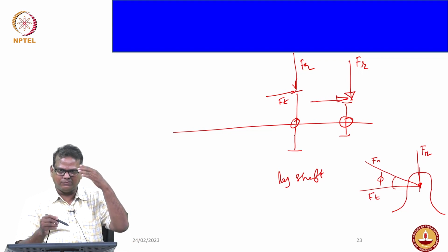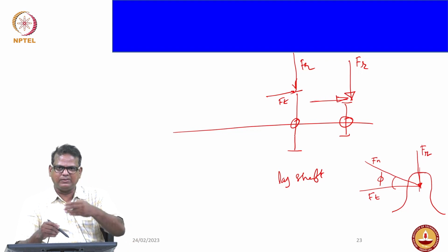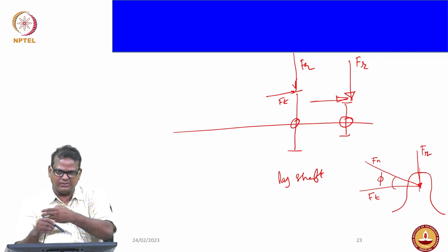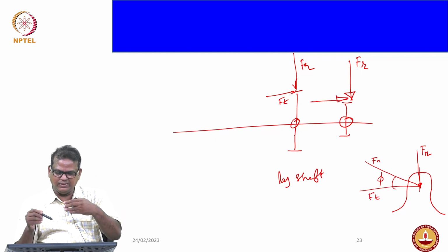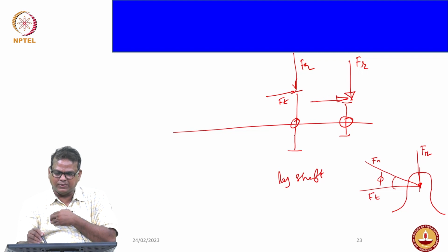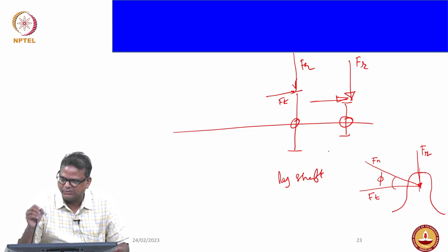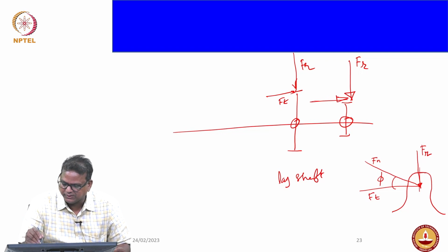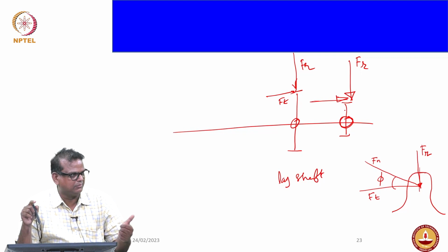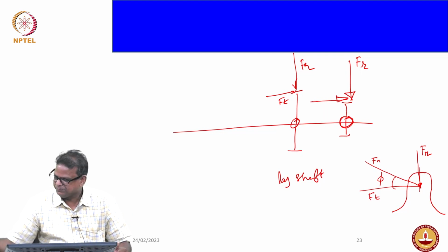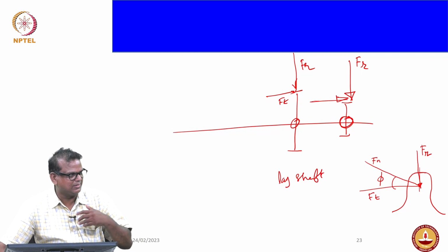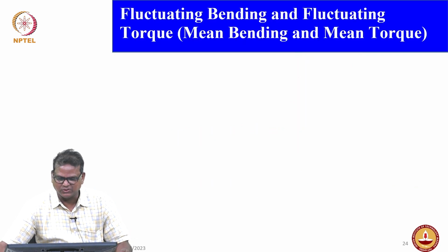You first split the shaft loads into vertical and horizontal, and for each gear do the calculation and find the moment. Then you take the square root of the sum of squares, I am sure you know that. Then find the corresponding diameter based on the constant torque and fully reversed bending. Okay, I am just giving you the concept because it will take a lot of time to solve the problem.